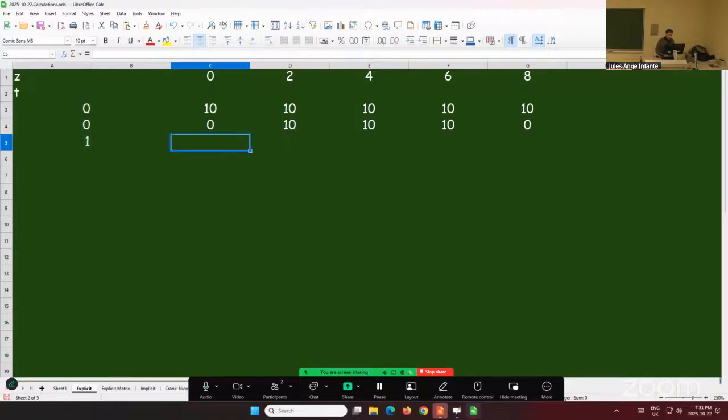And now here I have my change in pore water pressures. At the boundaries, my boundaries are controlled. Here I say I have R times the left node plus one minus two R times my same node from the previous time step, plus R times the following node.